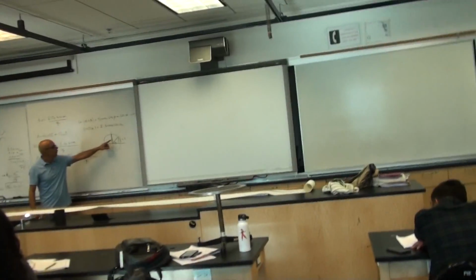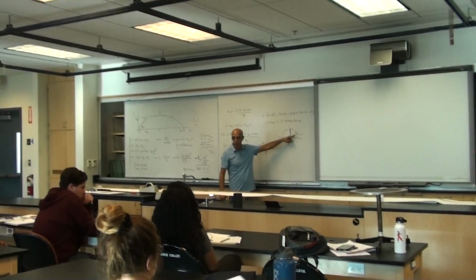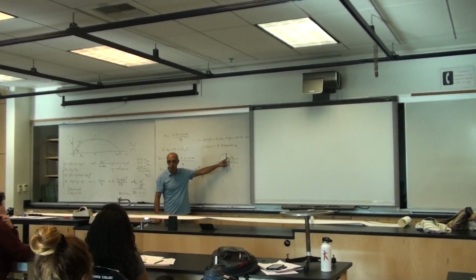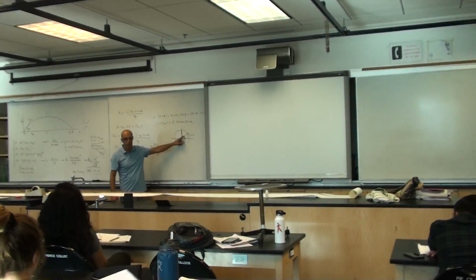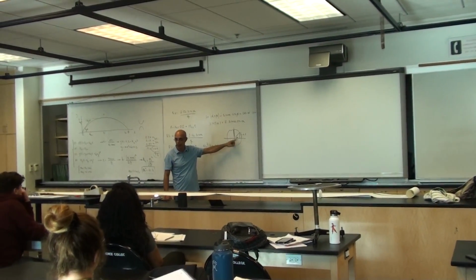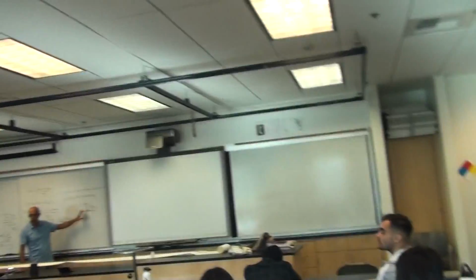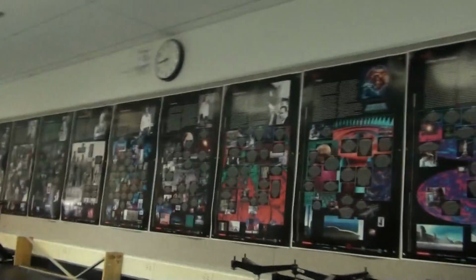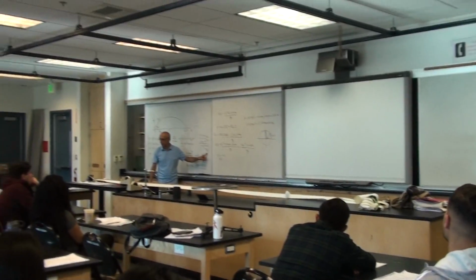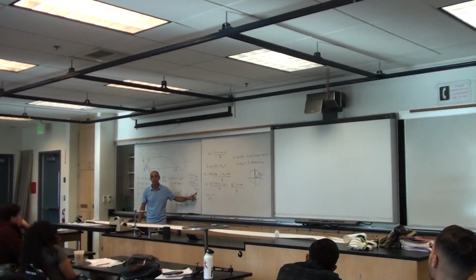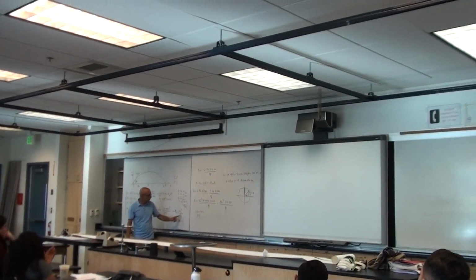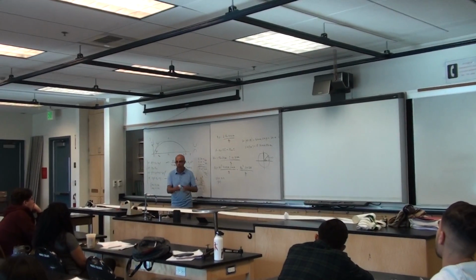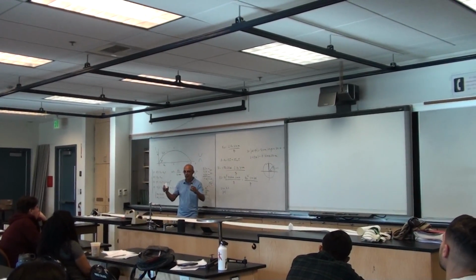If we estimate the error here by 1 degree plus or minus, if you calculate the sine of 60 and the sine of 58, you're going to see that this is going to be about another 2%. So 2% plus 7% makes 9% of error. We need to calculate how much that's going to be here, so I can plug in my tolerance.